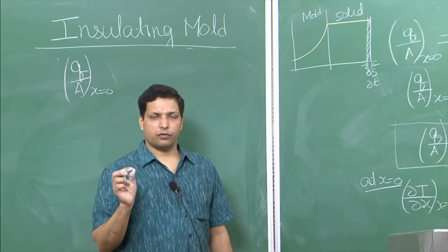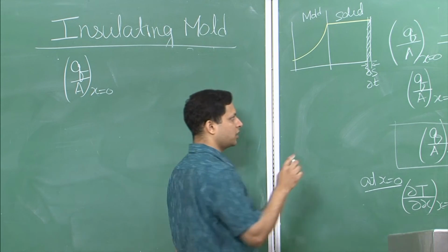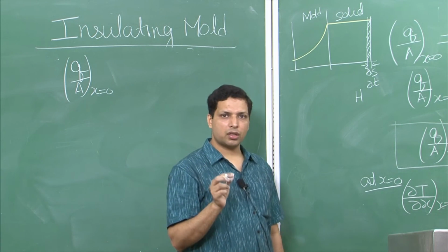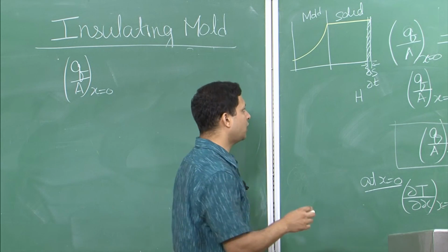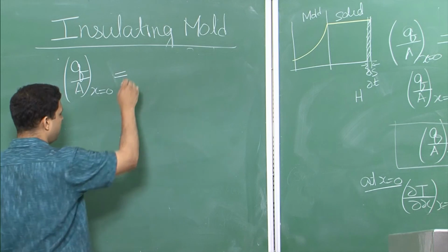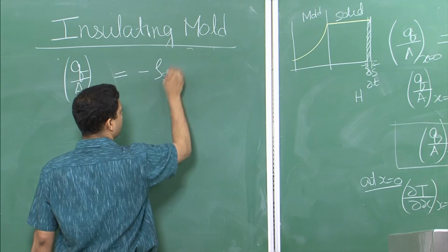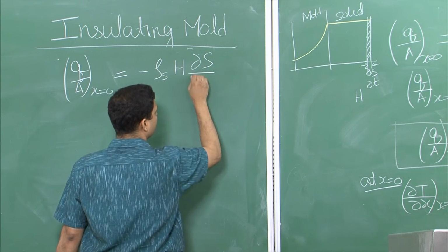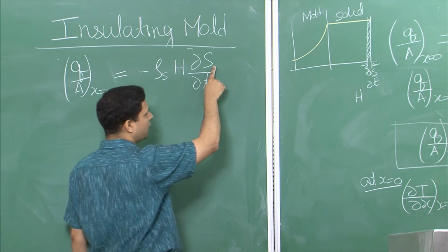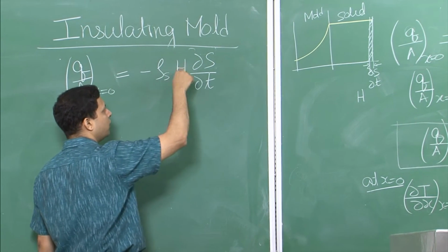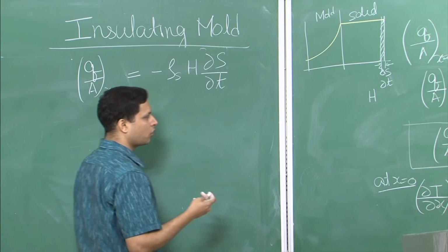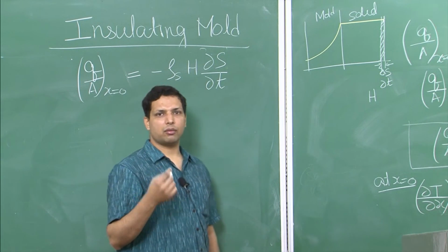Now, whenever this solid forms, some amount of heat is released. What is that heat? It is heat of fusion. So, depending upon the amount of liquid that has solidified, that will be the equivalent amount of heat that is released, and therefore, Q over A can also be written as, meaning in del T this del S length has solidified, and proportional to that is the amount of heat that has been generated, because when the liquid solidifies, some amount of heat is released.